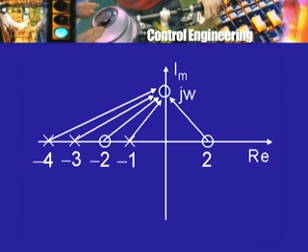So, qualitatively then we know that the low frequency gain will have some finite value which can in fact be calculated, and the high frequency gain will be 0. This much for the gain. What about the phase shift? Well, look at the vectors drawn from the zeros and the poles to this point j omega. Therefore, there are these various vectors, and look at the angles made by them with the positive real axis. Add the angles made by the zeros, from that subtract the sum of the angles made by the poles, and see what the result is going to be.